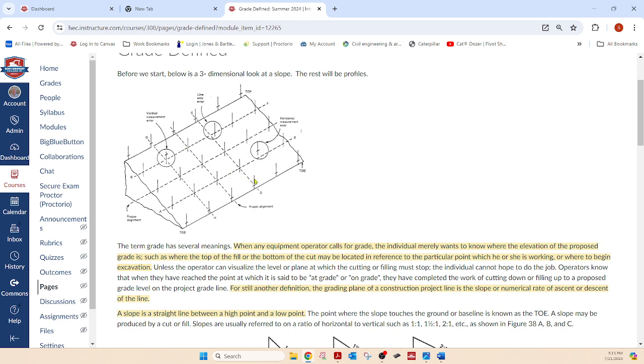So there are some things to point out here. It's real important that these stakes are truly aligned. They're saying this one's off a little bit in this direction, but you need to be diagonally aligned. That's how important it is to get these stakes right. When you put a stake in the ground, it needs to be plumb and solid in the ground, and it needs to line up with the line where all the other stakes are, both this way and that way, and diagonally. So all that needs to be done.